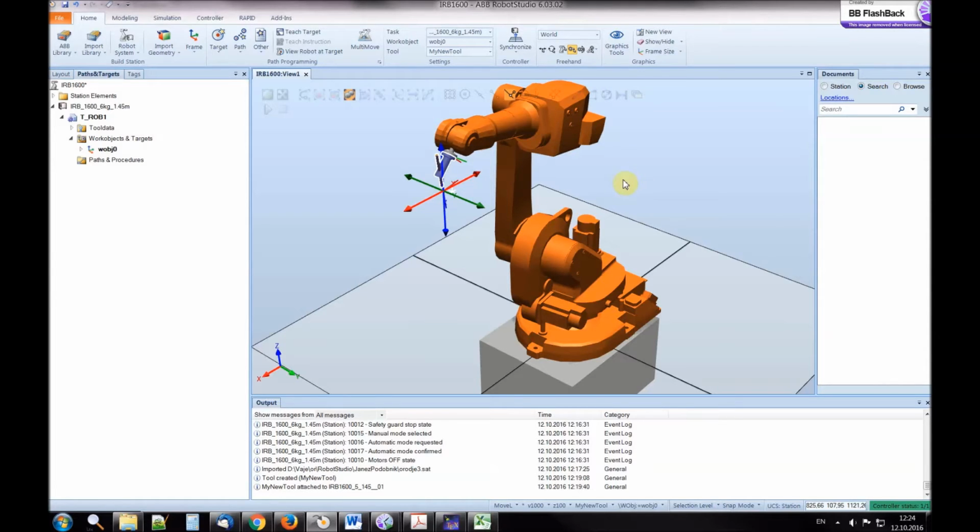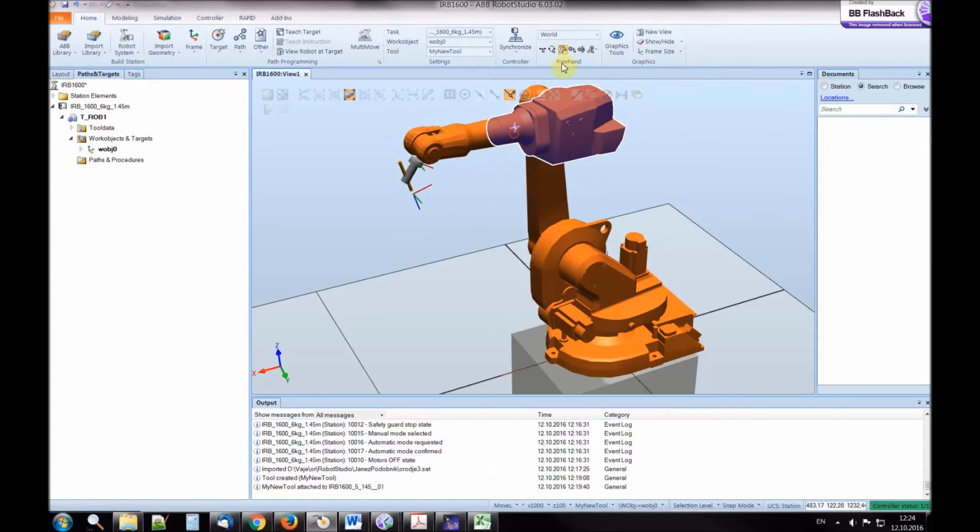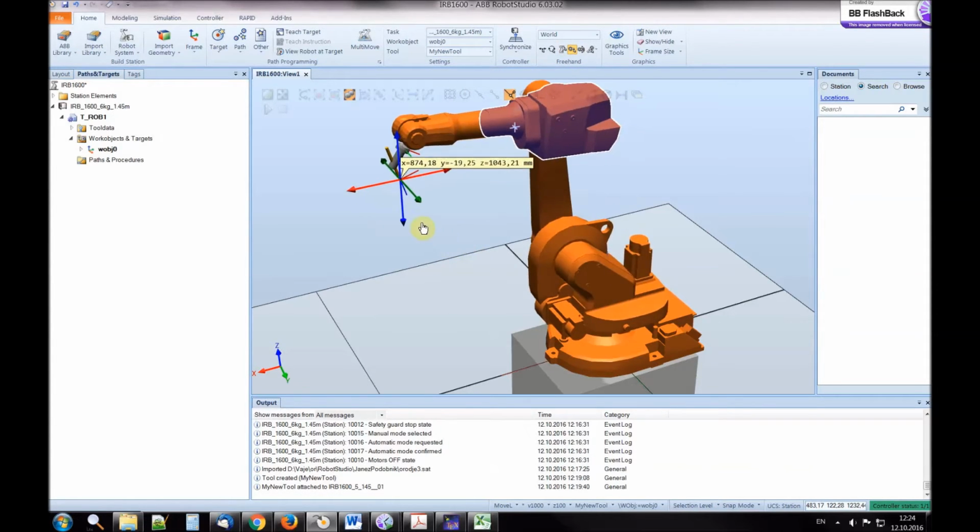And you will create also the coordinate frame which will be attached to our object, to the aluminum block. And this will be, of course, the local coordinate frame of the work object. So these are the main ways how you can move the robots. So joint space and external space. And when you program the robot, you will also be able to use move instructions related to both spaces. So one will be move joint, so in joint space, and the other will be in the external frame, so move linear. I will explain that in more detail when we come to the writing of the program.